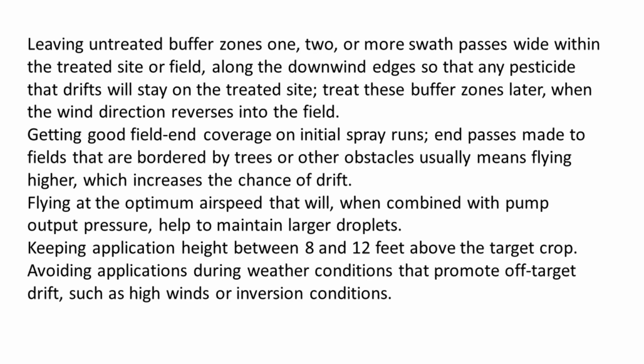Getting good field-in coverage on initial spray runs, in-passes made to fields that are bordered by trees or other obstacles, usually means flying higher, which increases the chance of drift. Flying at the optimum airspeed that will, when combined with pump output pressure, help to maintain larger droplets. Keeping application height between 8 and 12 feet above the target crop. Avoiding applications during weather conditions that promote off-target drift, such as high winds or inversion conditions.